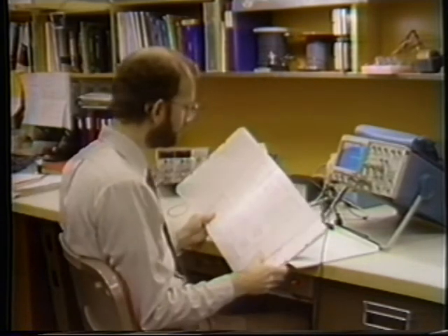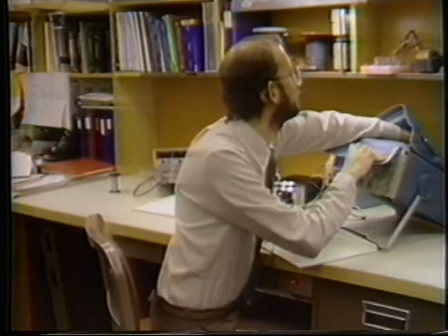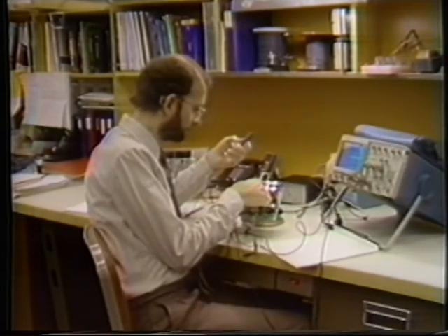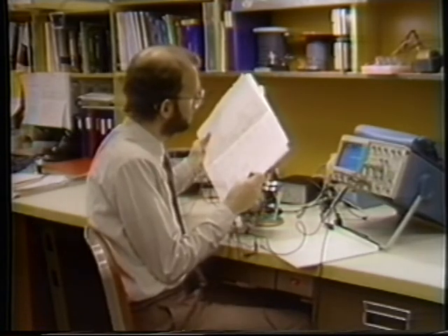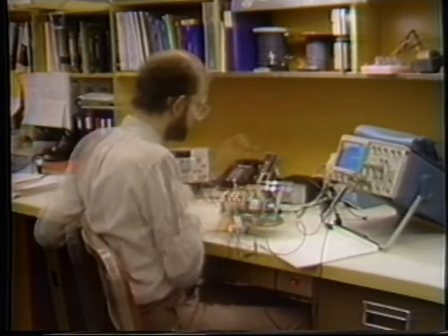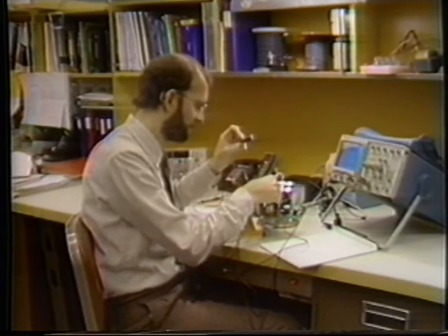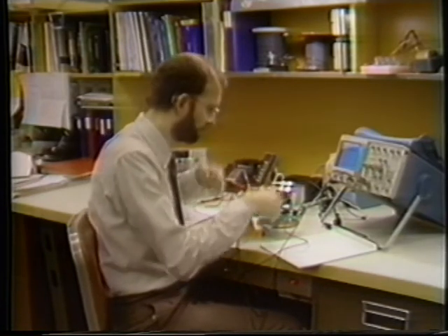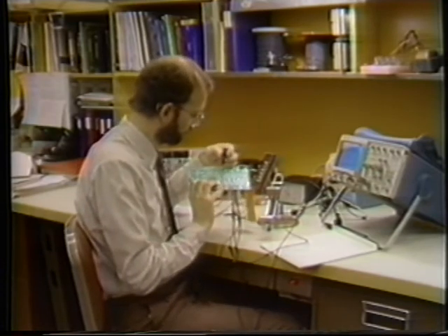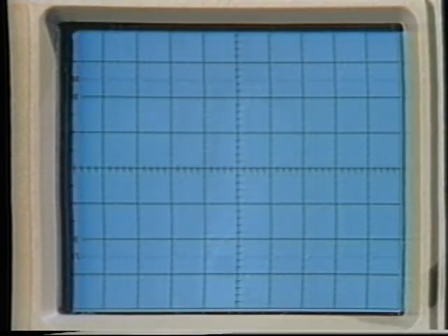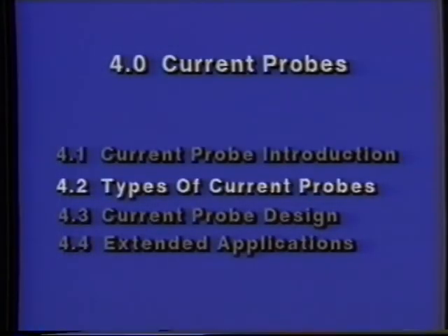Of course, there are problems. If the resistor doesn't have one end at ground, you'll need another differential probe. The capacitance loading of, say, a 10x probe could change the high frequency characteristics. The value of that existing resistor must be known very accurately. Any deviation will directly throw off all your other measurements. And adding resistance might lock up the circuit anyway.